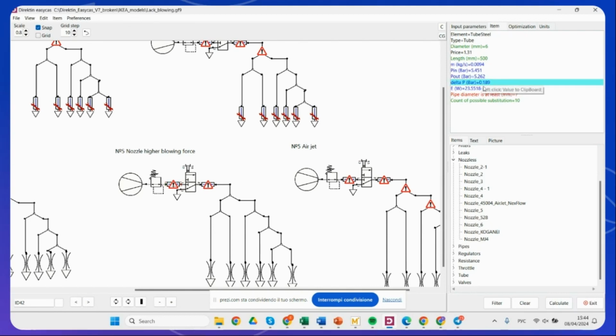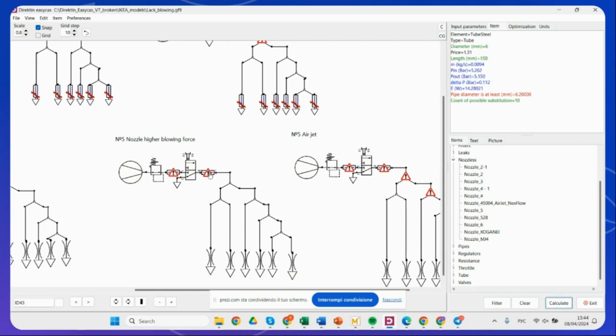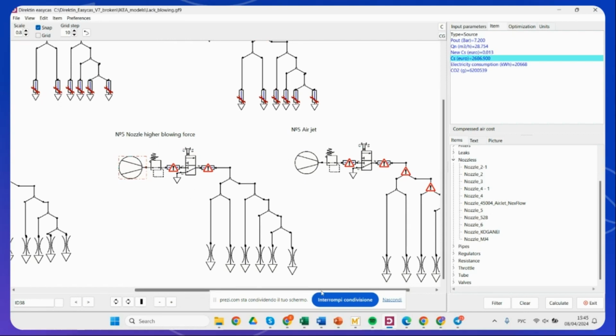Here it is 0.2 bar, which means that we have 0.3 bar of pressure drops just for such a small system. So you can also see how much it's going to cost. It's more efficient. Of course, it's better than the open tubes. However, we always need to remember about changing the components afterwards. So we cannot just change one component and hope for the best. We need to check the design also before.